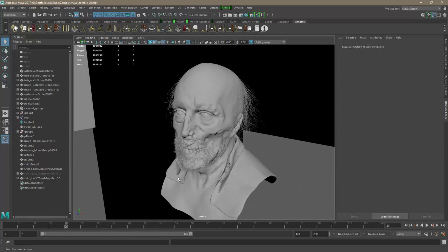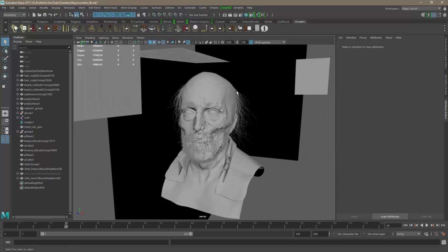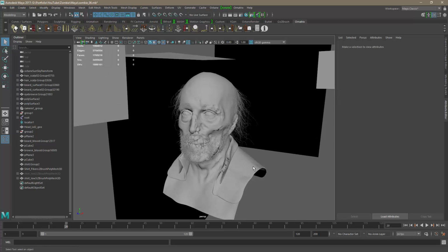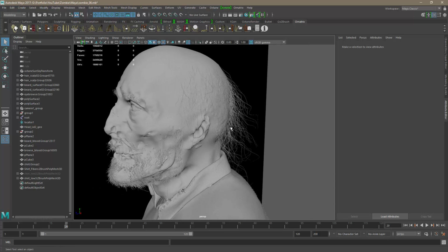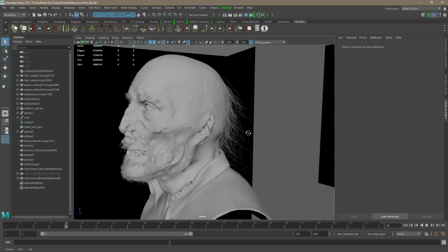So for the geometry, we are gonna export everything in OBJ, and then for the hair and beard and eyelash and eyebrows and things like that, basically everything that we made with Ornatrix for Maya, all of these items will be exported as Alembic, because Octane Render standalone actually can render properly the hair using its own proprietary hair primitive.